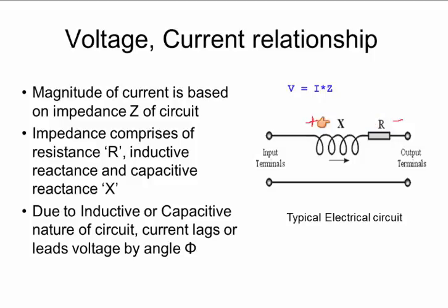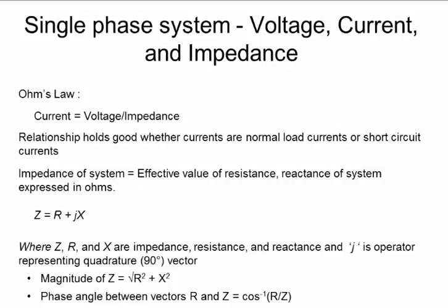That's why it dissipates. With an inductor, they are always 90 degrees out of phase. It's similar with a capacitor. So when they are out of phase by 90 degrees, there's no dissipation. It's simply reactance. In other words, it stores energy and then releases it in the next half cycle. So this is just some basics on Ohm's law for complex impedance circuits.